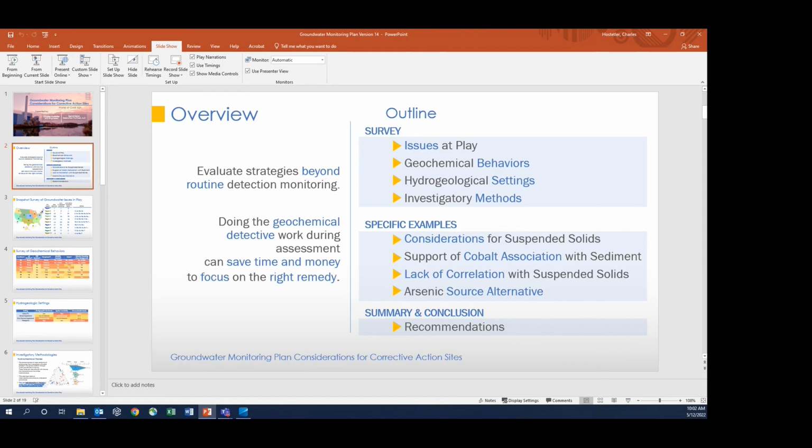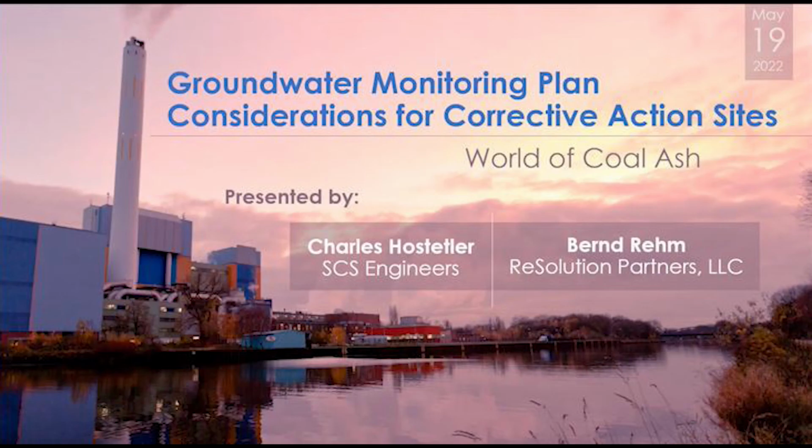I very much enjoyed your presentation, guys. You talked a little bit about one of the things that you suggest doing in addition to what's required in the regulations, which is something that I guess the regulations forbid. They say you shall not field filter groundwater samples, and some regulators won't even consider those data. But I take it your point is that whether or not the regulations permit field filtering, it should be done anyway to understand what's going on in the aquifer.